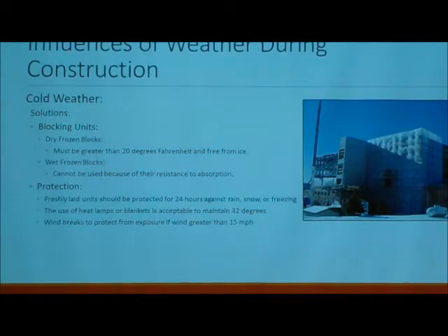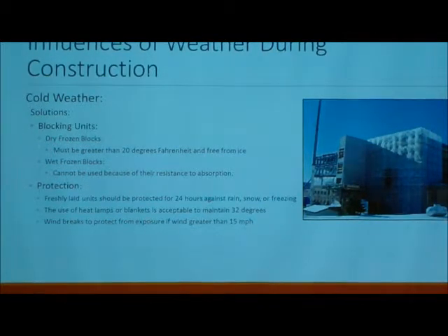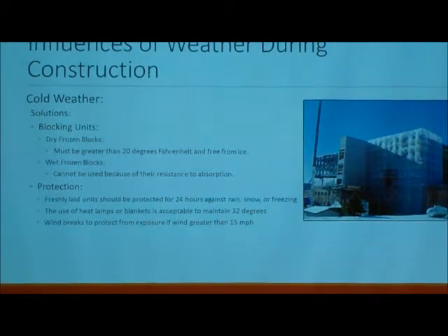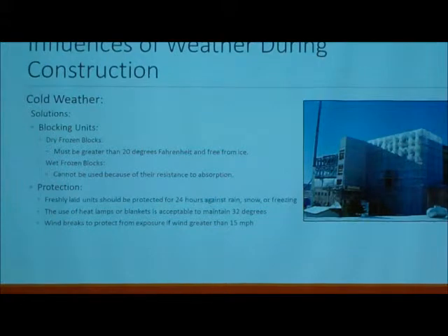So, some other solutions. For dry frozen blocks, they must be greater than 20 degrees Fahrenheit and free from ice. The ice on the bricks would prohibit the water from penetrating into the bricks, and that would be that bond reduction we were talking about. And then any wet bricks can't be used, because of that poor absorption rate.